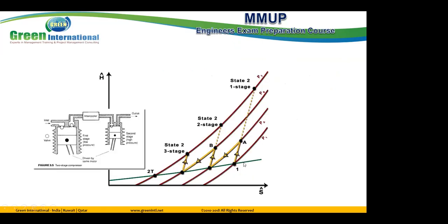See with me here, also the same. This one from pressure 1 up to pressure 2 is the direct pressure line. But if you go to intermediate pressure A and then make cooling, then continue to pressure B, then cooling and continue again to the final point 2, we find this part plus this part plus this part. It is surely less than going from 1 to 2 directly.